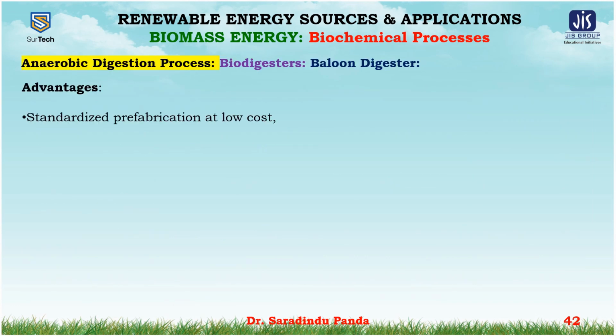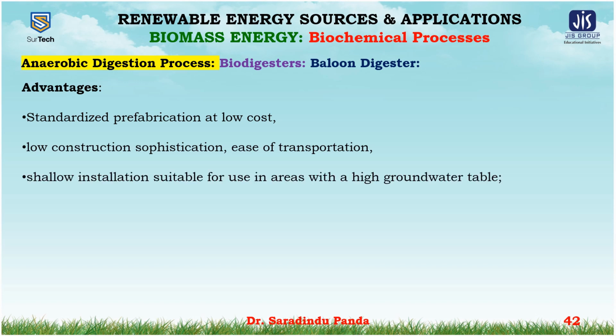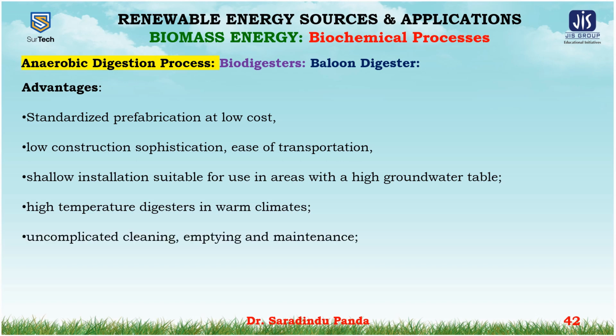The advantages of the balloon digesters are standardized prefabrication at low cost, low construction sophistication, ease of transportation, shallow installation suitable for use in areas with a high groundwater table, high temperature digesters in warm climates, uncomplicated cleaning, emptying and maintenance, and difficult substrates like water hyacinth can be used.